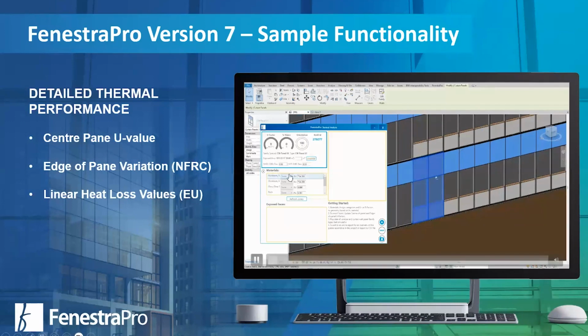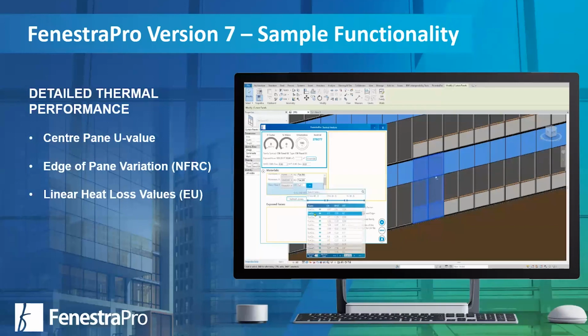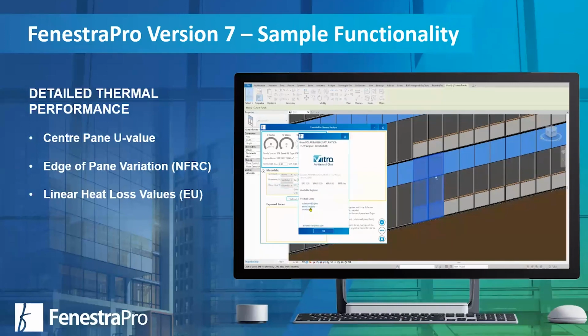And within that, as you start adding in and defining the components, and this could be something as sophisticated as a customized panel with nested components, or something as simple as a punched window within the building, where you're adding those variations. So you'll see, for example, in the US, we look at the edge of pane variation. So that's a 2-inch variation, that center pane U value, based on those edge conditions. So it's an edge of pane value under NFRC.